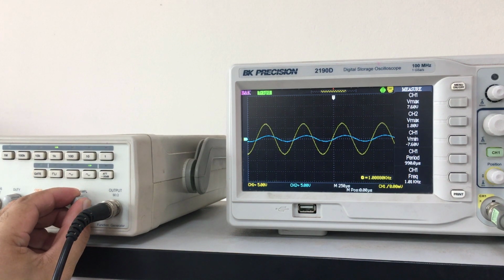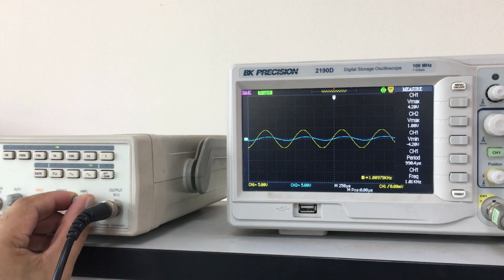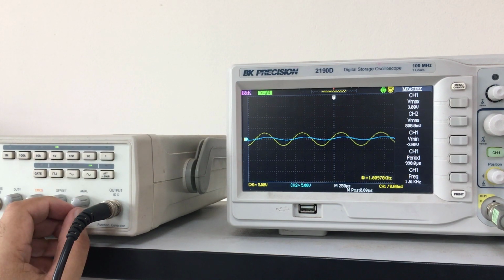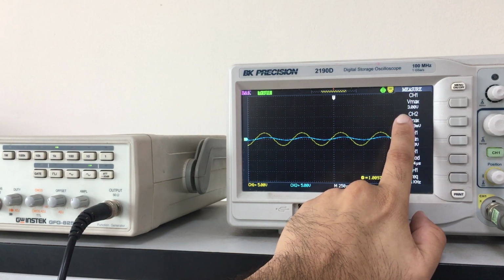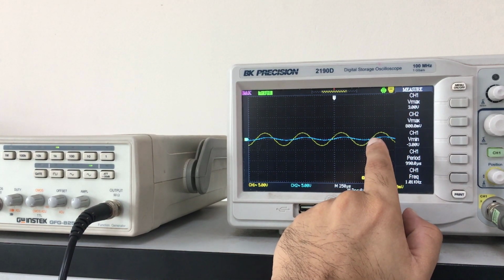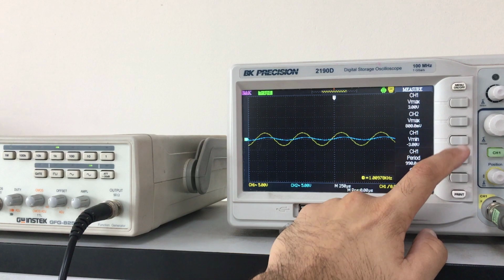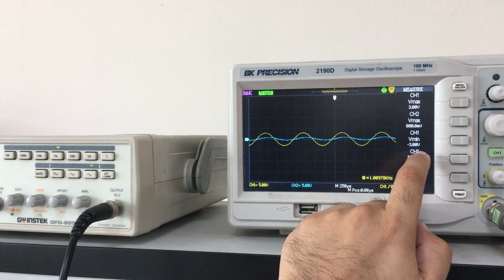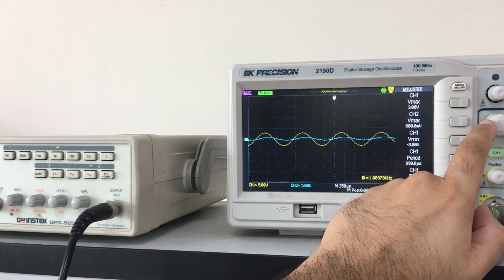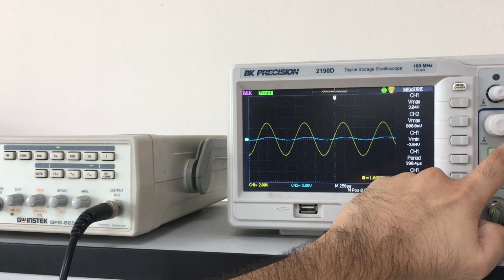By adjusting the amplitude, reducing the amplitude, okay. So now we see that the channel 1 Vmax is 3 volt, which is 3 volt peak. So we have calibrated our source to 3 volt peak and 1 kilohertz. So now we see that since the waveform size is reduced, we can decrease the volt per division so that the waveform is a bit clearer.